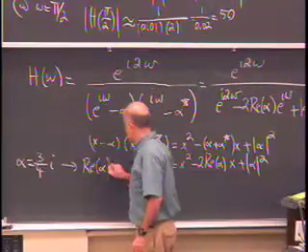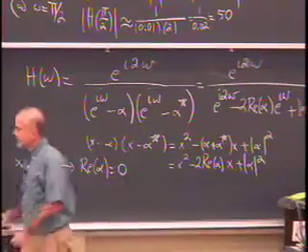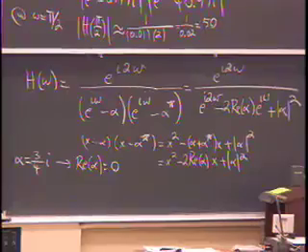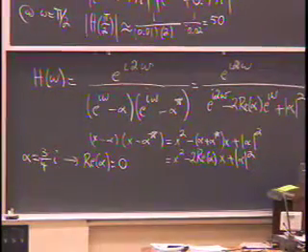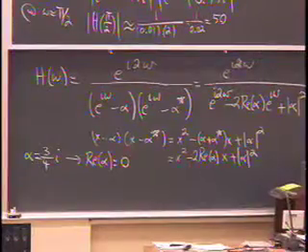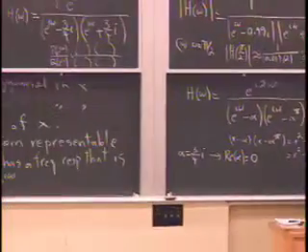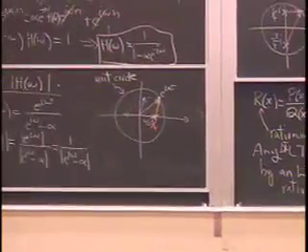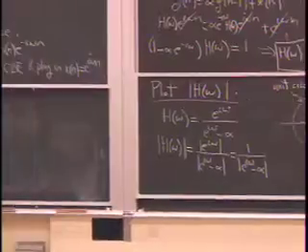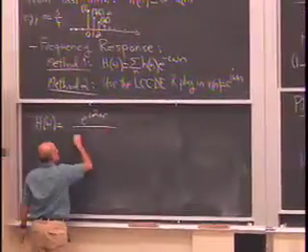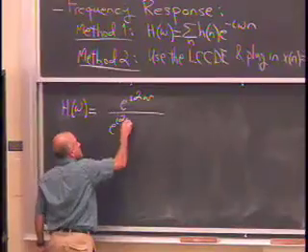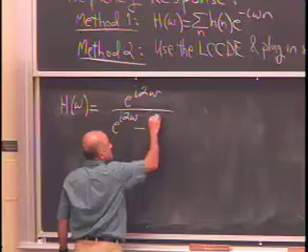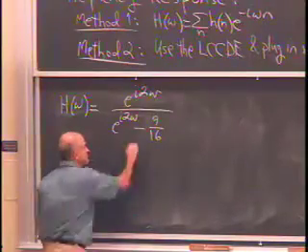So when alpha is 3/4 i, the real part of alpha equals 0. And now I can write the frequency response in a slightly more amenable way, amenable to converting to a difference equation. So I have H of omega equals e to the i 2 omega over e to the i 2 omega plus magnitude squared, 9 over 16.